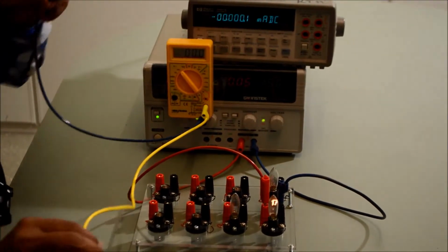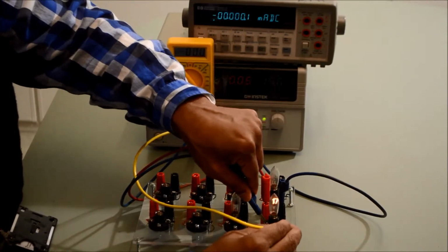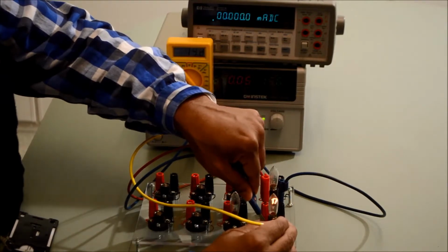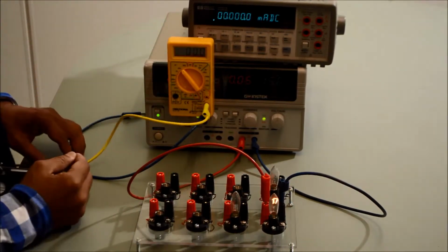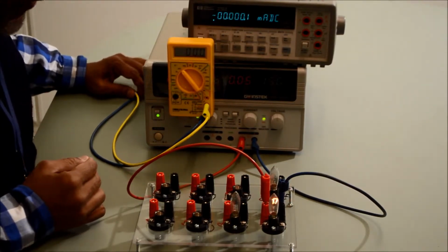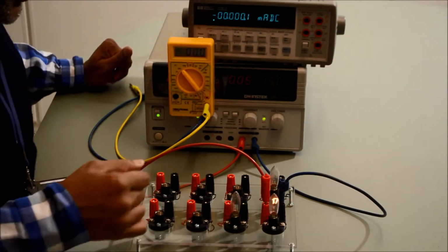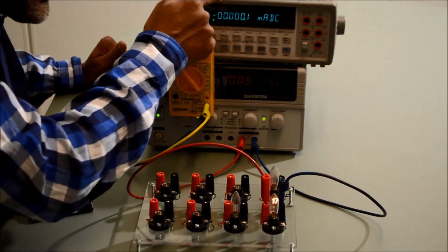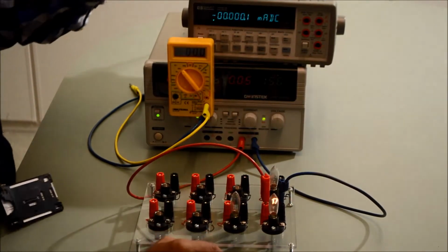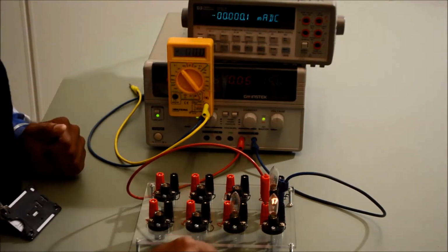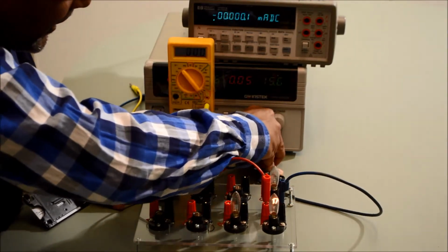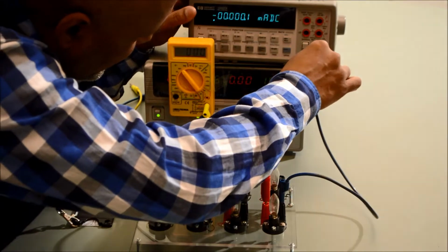Measuring voltage, you just make sure that you get the same voltage. So the voltmeter is connected to the same voltage that is across the lamp. Now for measuring the current, the connection should be a little different. And how is that? We want the same current to pass through the amperemeter that passes through the lamp. And that means we need to connect the amperemeter in series. So same current should pass. That means we need to connect in series. That's what we do.